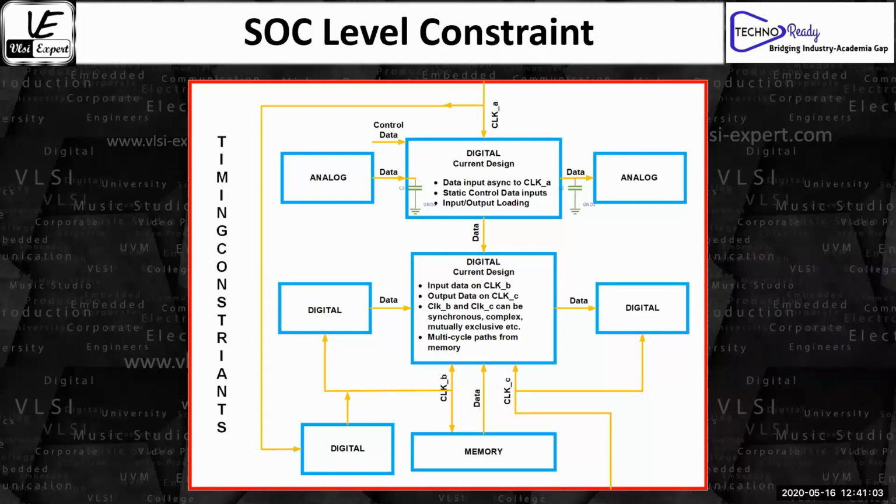In a typical flow, and it depends on the company, I'm just mentioning the usual flow, you run the block through synthesis. Once it meets all the timing, the synthesis tool tries to optimize the area without violating any timing constraints. It depends on how you set up the flow, in the synthesis setup. If you prioritize area, then it will optimize the area and it may leave some timing violations. As I said, this is a very good question because this brings us to the trade-off. You can do the same thing with power.